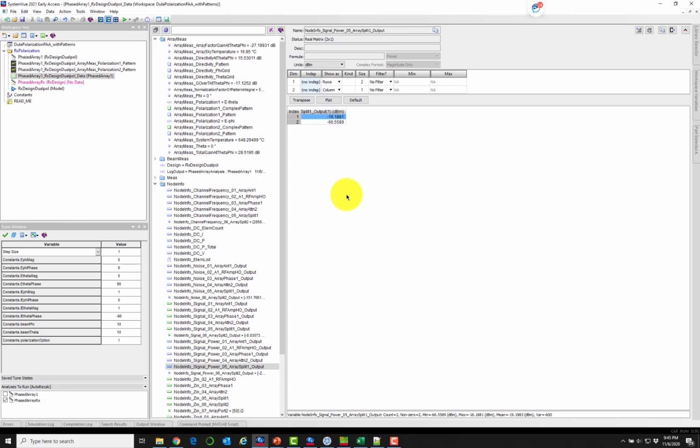But since here the antenna is a practical antenna, it's not an ideal mathematical antenna, it will have some kind of a response even to the other type of polarization, even though it is very small. That is why here the E phi antennas were able to pick up small values, a small contribution of E theta, and then produce an output here. This represents a more practical situation.